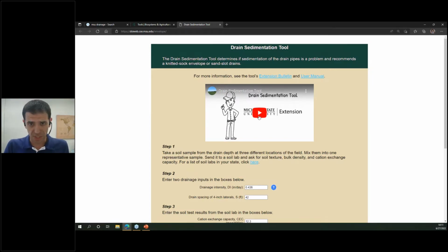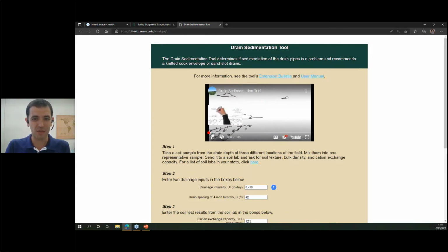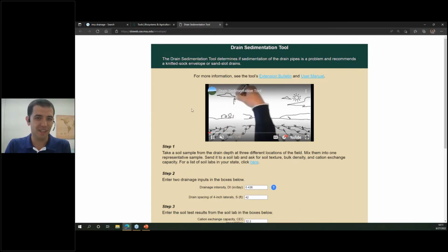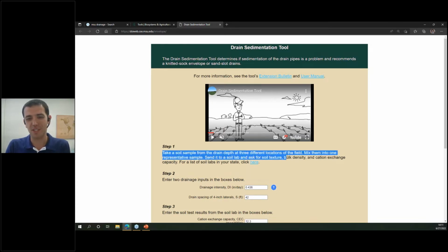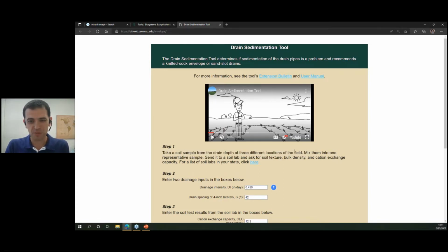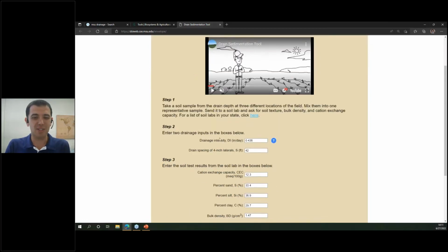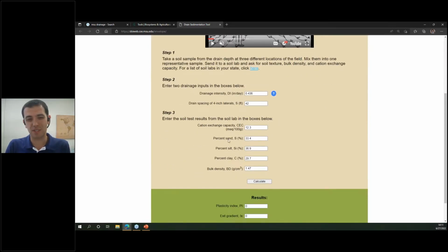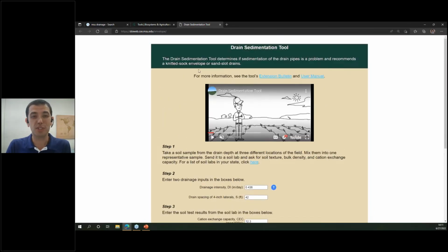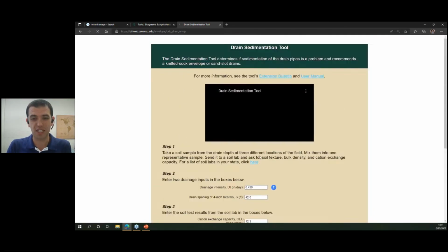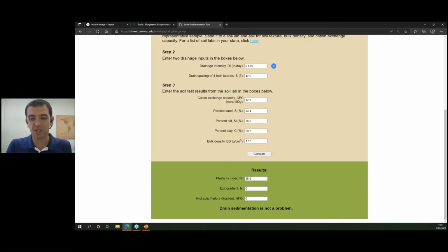There's one of these videos here. I don't have time to show it to you, but it's one of those cartoons that explains it to you. So you're welcome to click on that and see how it's used. For this tool, all you need is a soil sample from the drain depth, and then you plug in that information, like the percent sand, silt, and clay, and then this tool will tell you, for example, when you hit calculate: drain sedimentation is not a problem.